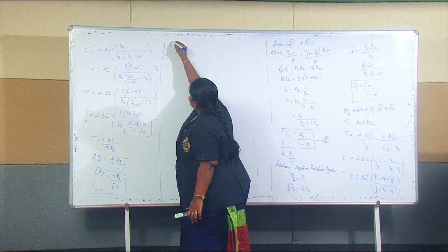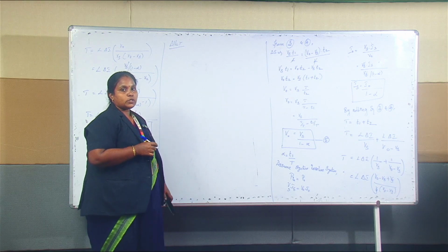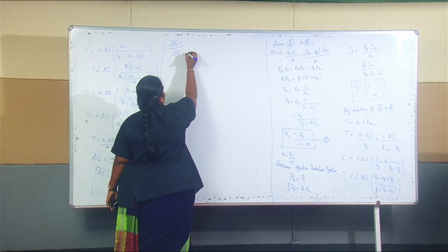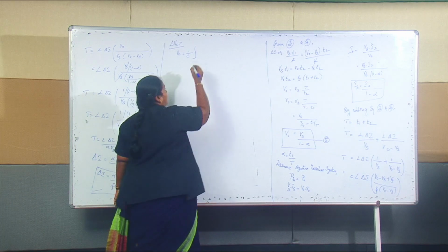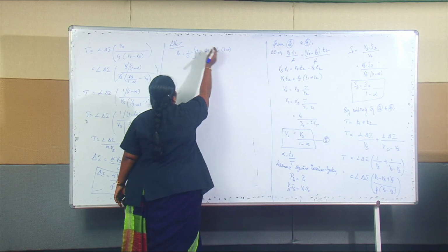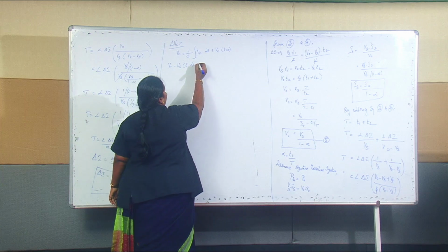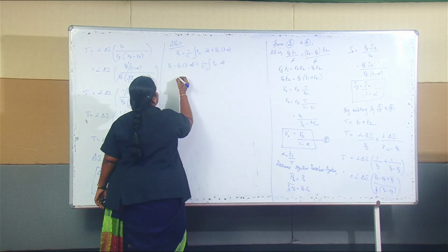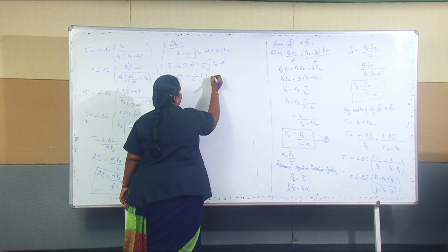which is del Vc. It is nothing but the ripple voltage across a capacitor. So this ripple voltage across a capacitor, we found this expression to be, let the voltage across a capacitor is 1 by C into integral of IC into dt plus its initial condition. When we bring this initial condition to this side, it will become Vc of t minus Vc of t equal to 0 is 1 by C integral Ic into dt. So this will become del Vc, which is 1 by C Ic into dt.